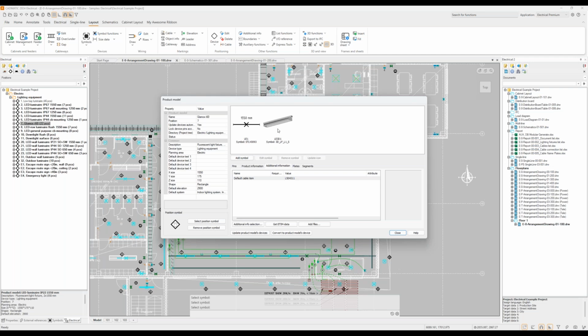Okay, so you can create any of these. You can have multiple symbols. For example, the safety switch has the arrangement drawing symbol. It had the one for the schema symbol, also some connectors or connections, and then it had some terminal strips as a symbol. So you can have all the symbols listed here, and when inserting to the drawing, you will just decide what kind of symbolics you will be using.